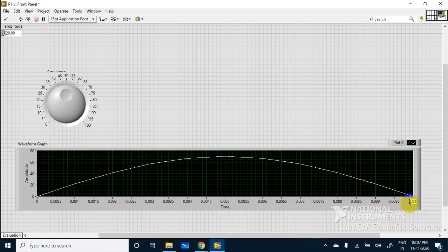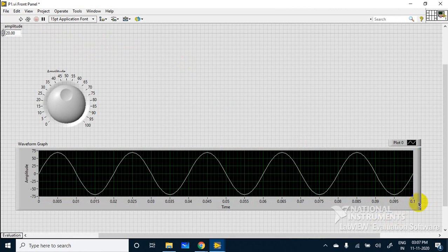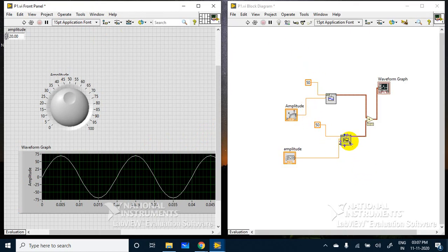Okay, 0.1, I can get it. Both the waveforms are in the same phase, that's why we are getting thicker lines. So this is the method to connect these waveforms with one CRO by using two channels.